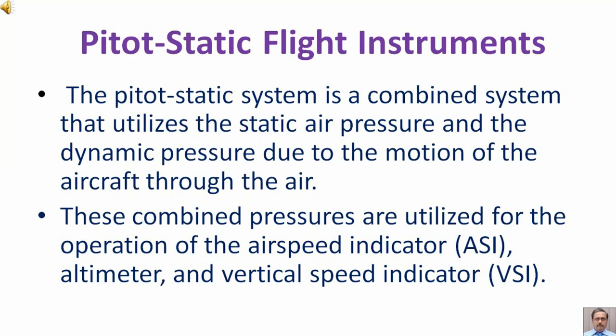Pitot-static flight instruments. The pitot-static system is a combined system that utilizes the static air pressure and the dynamic pressure due to the motion of the aircraft through the air.